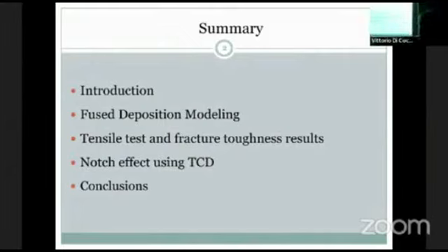Okay. So a short summary of my presentation. We use fused deposition modeling to print some specimens in order to investigate the notch and size effect. We did the tensile and fracture toughness static tests, and then we tried to apply the theory of critical distance in order to investigate the notch effect.